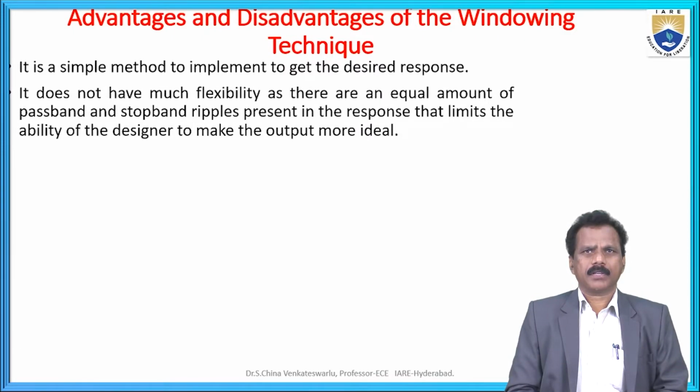It does not have much flexibility as there are equal amounts of passband and stopband ripples. The passband and stopband ripples present in the response limit the ability of the designer to make the output more ideal.